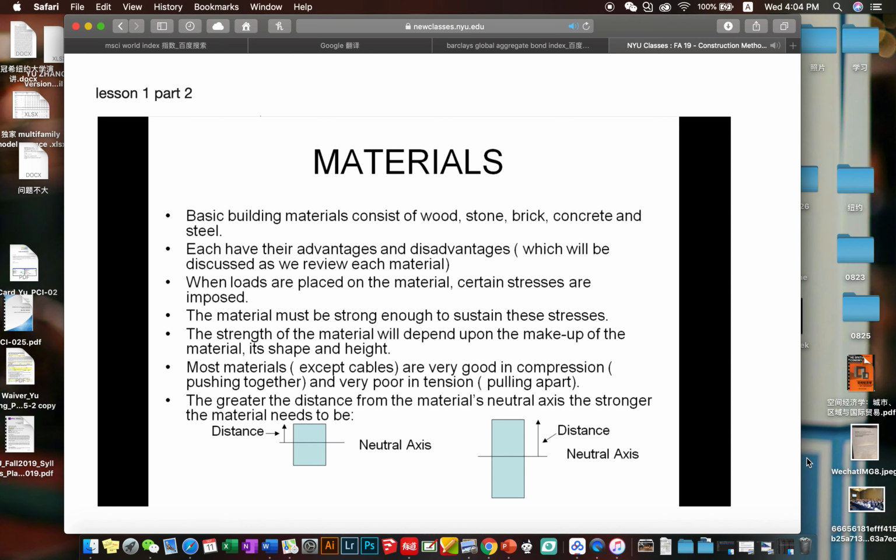If you've got a short distance from end to end where it's being supported, and it's a weak material, it can probably hold a larger weight than if you had that same material expanded 2 to 3 times the same length. All right, so you picture a board supported between 2 concrete blocks, or a horse structure, or anything of that nature, and that point load in the middle can be a lot heavier if the supports are closer. But the further the supports go out, the stronger that material has to be to hold the same weight.